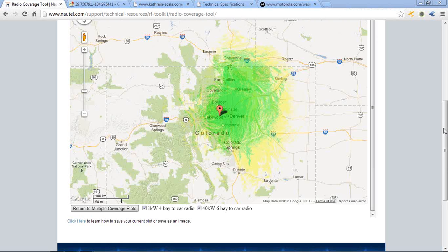Okay, based on the tests I made in the field: if you take 50%, that will be no statistic at all. This is the average signal. By putting 70, you make the program a little bit pessimistic. This is what I observed in the field: if I use 50%, every number that I get from the model is too optimistic. If I select 70%, I see that most of my measurements fit the prediction, and those that are off are equally distributed, both optimistic and pessimistic. So I used 70% as a default value. If you use that value, you should see a correspondence between your measurements in the field and the prediction of the program.